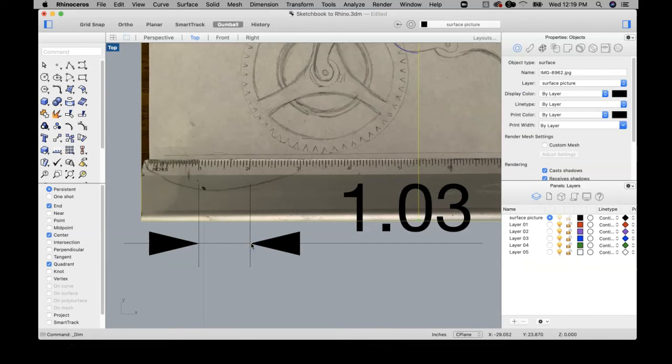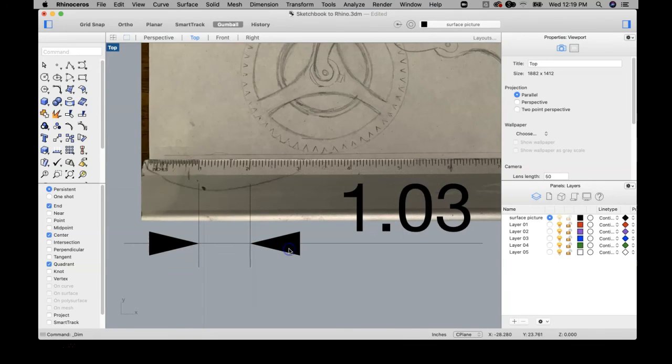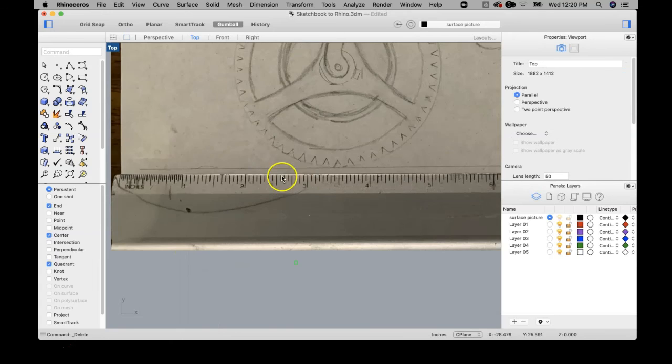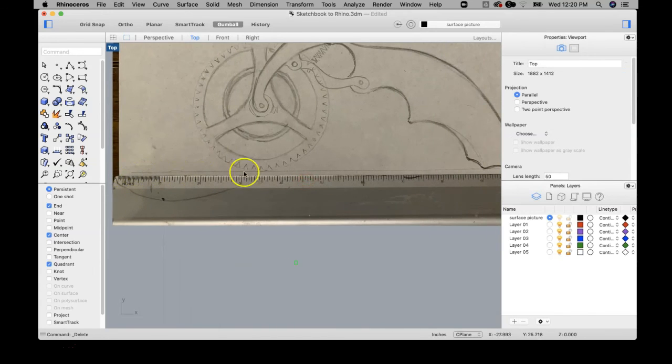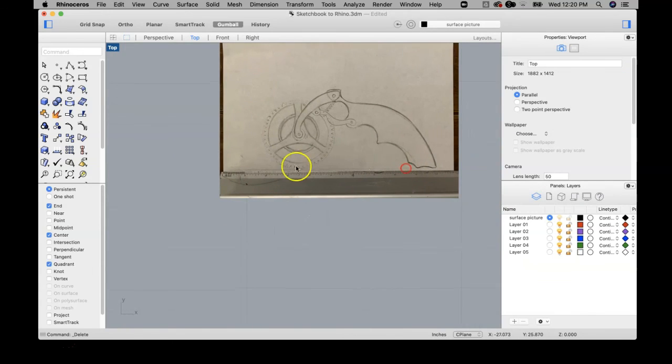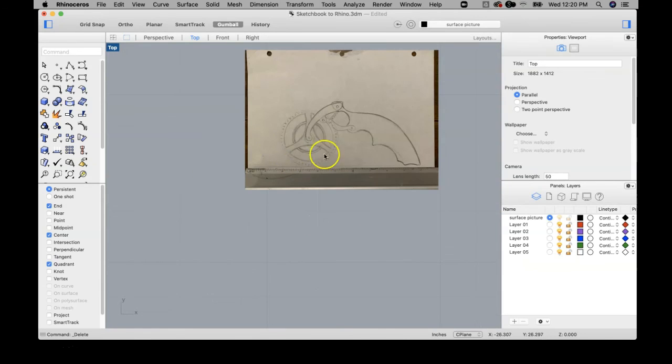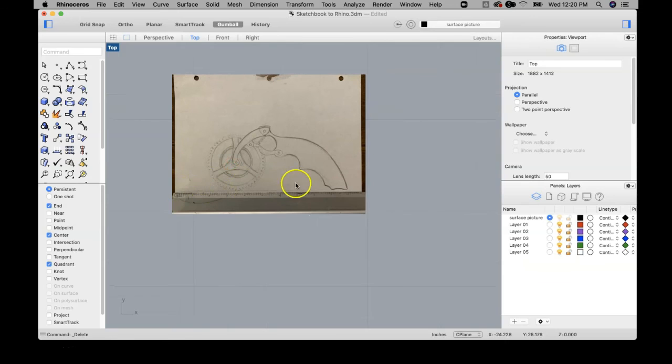So this is really accurate. And again, who knows how close I located those 2 points that I isolated there. But the longer the ruler, the longer that dimension, typically, you wouldn't want to scale it based on 1 inch. When we first scale it, we probably want to scale it on as large a surface as we can, and we'll have greater accuracy that way.